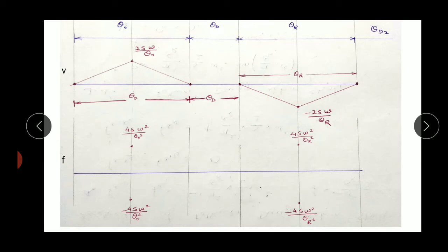From the start of the outstroke, you can observe that the velocity is continuously rising. As velocity is continuously rising in this graph, its slope is positive. Slope's equation is y2 minus y1 divided by x2 minus x1. As slope is positive from the start till the middle of our stroke, that means there is constant positive acceleration. So during the first half of outstroke, the acceleration is positive.